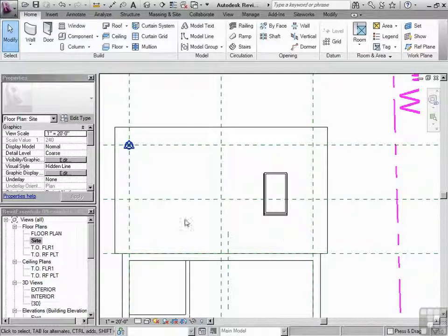So we want two skylights, we want them centered. So we want the same distance between, there would be 1, 2, 3 spaces between two skylights. And we want that space to be the same. That's what they would consider to be centered. So how do we do that? Well, we can just take the size of this. This is 24 inches wide. And we can take the total length between here and here, that's 17 feet.